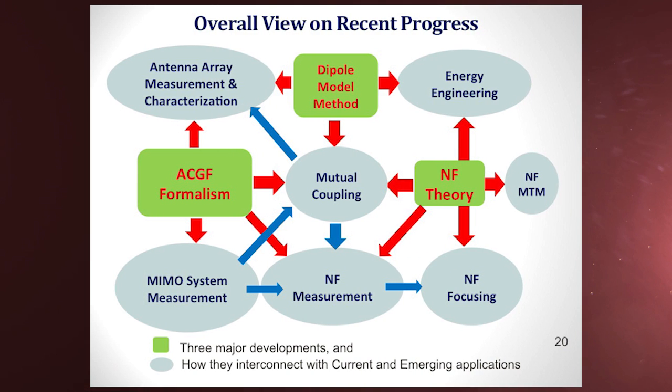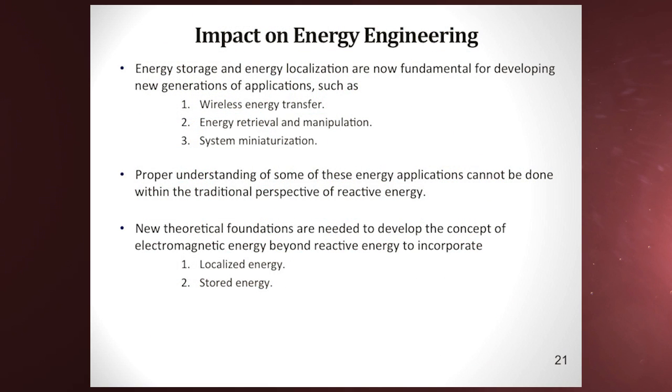If you're talking about near field focusing, when I say near field focusing here, you want to have a certain radiation pattern. So how do you design the near field of the antenna to get that radiation pattern? Near field metamaterial: most of the work done in metamaterial is temporal. We're looking at a spatial variation of the energy around and so on. Mutual coupling: it's not a circuit concept. We're looking here at the field concept.